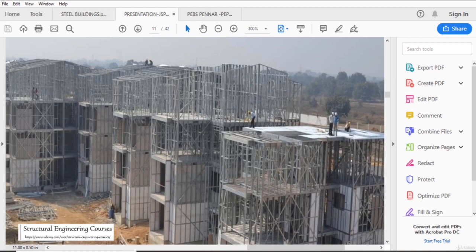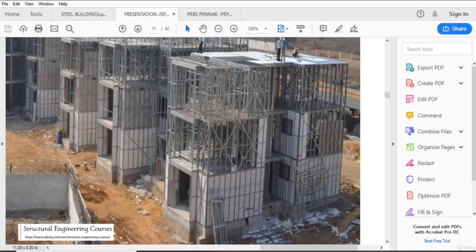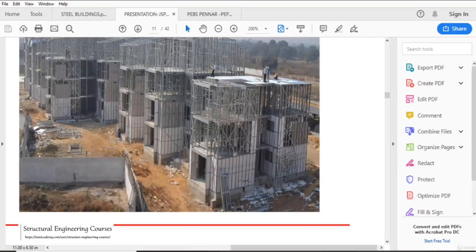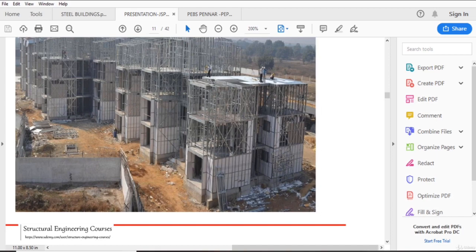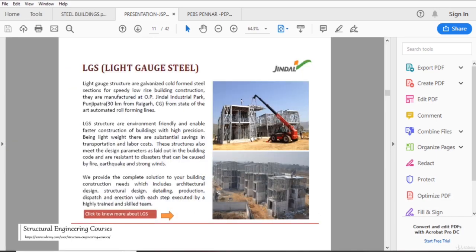So it serves as the wall. Each and every member serves as a structural steel part, and it provides the stability. In simple words, here you can see that there are no strong columns, that is, I section structural steel. Why are there no columns here? Because each and every member acts like a load transferring element from top to bottom, and in addition we are also providing the bracing here. So these are, I must say, kind of Lego blocks that we can just interlock, and we can make very beautiful and cost effective buildings with the help of this approach.